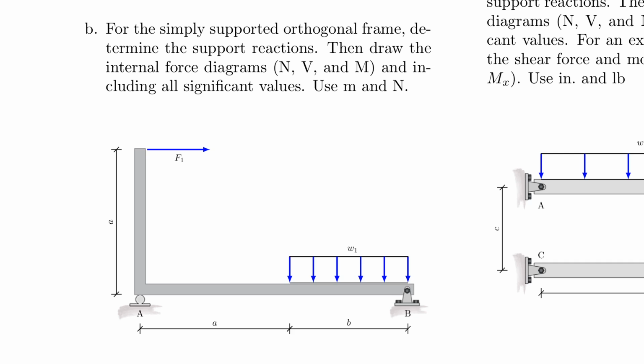And once again, you want to identify where your reference fiber is. For this problem, the way I would do it is just on the bottom, as I always do, and then I also choose the inside. You could have, for example, also moved this reference fiber to the top just for practice purposes, or you could put this to the outside, then it would pretty much line up with this one. It's up to you, but my personal convention is inside and bottom. That's how I usually do it.